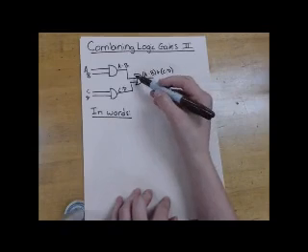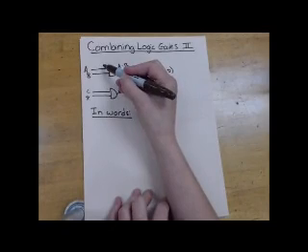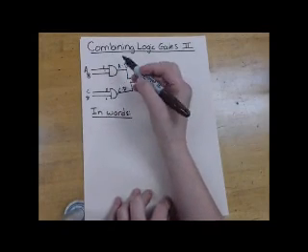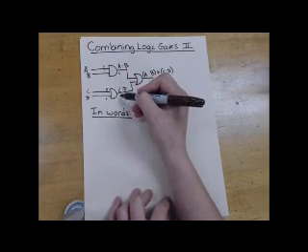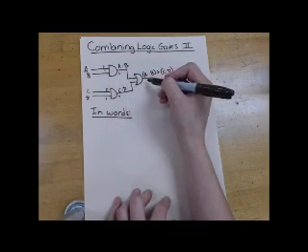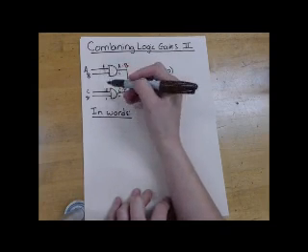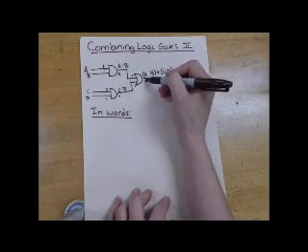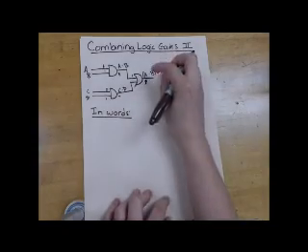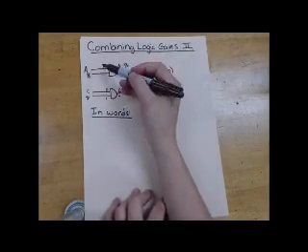So what this will do is, if any of these are zeros, so for example 0, 1, 0, 1, this will give us a 0 output because this AND sees a 0, and then both of these zeros will give a 0 for the out. But if either one of these inputs has two 1s in it, so for example 1, 1, 0, 1, this will give a 1, this will give a 0, but a 1 and a 0 for an OR gate gives us a 1. So in words, this OR gate basically finds if there are any pairs of 1s for these A, B, C, and D.